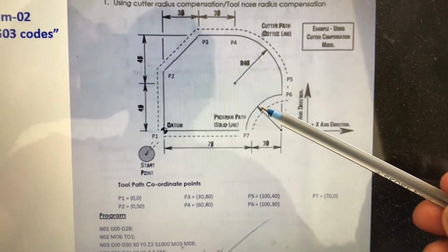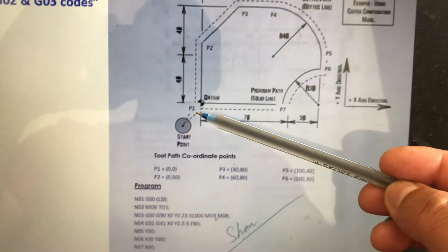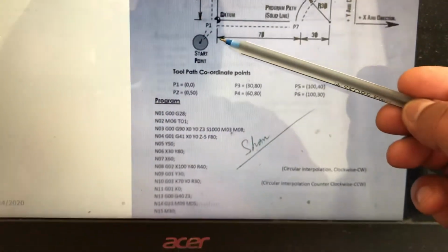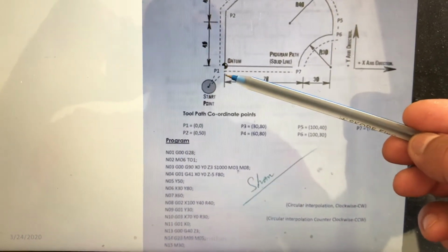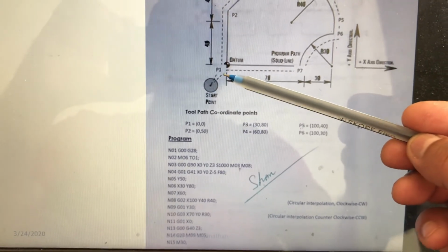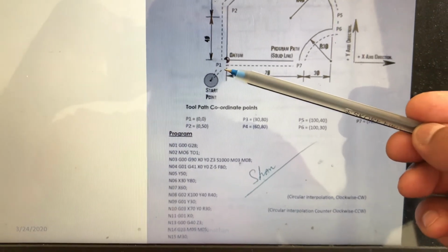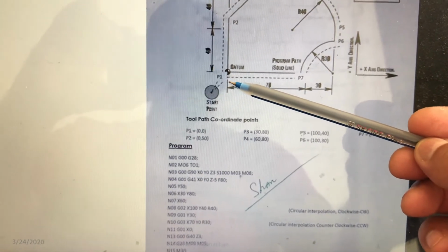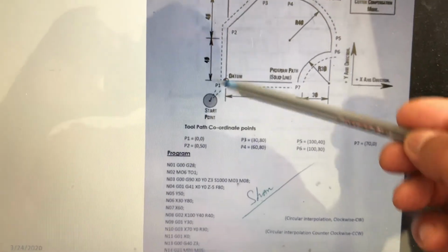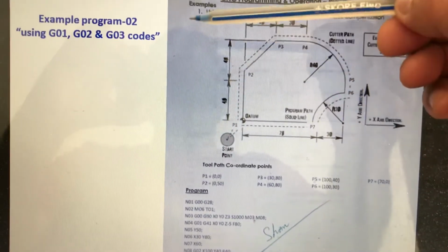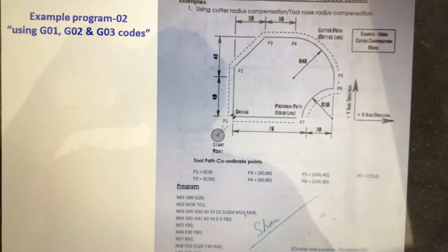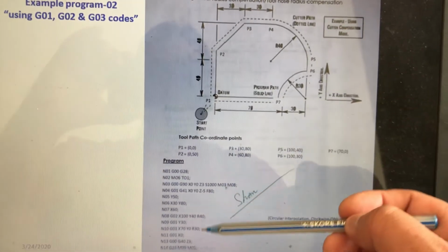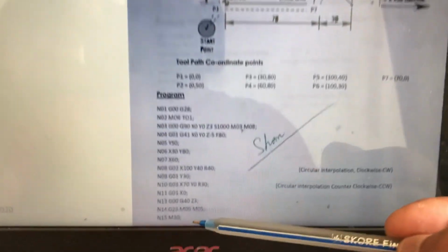This will be G03, and then again G01, and goes back, cancel tool nose radius compensation G40, and stop the spindle, stop the coolant, take Z above surface of workpiece, that is give Z value as positive value, Z plus 2, plus 3 etc., and then go to machine zero point or machine home point, that is Z20 G28, and finally end program, that is M30.